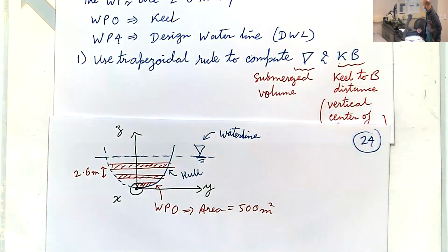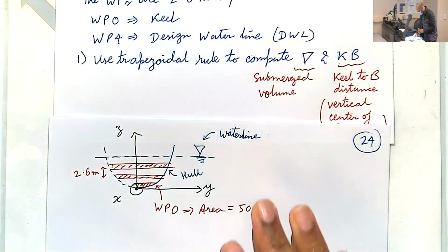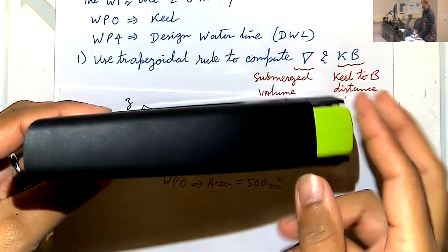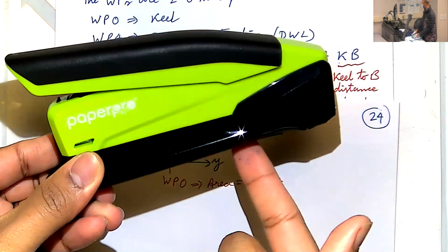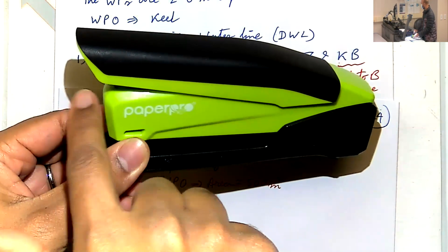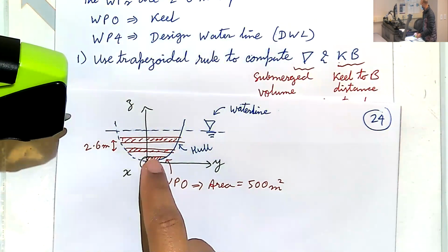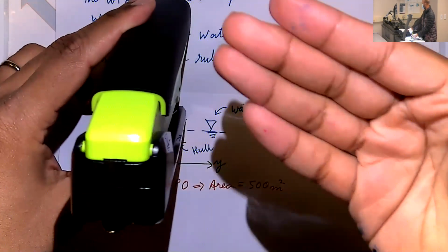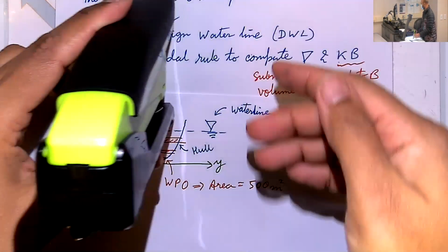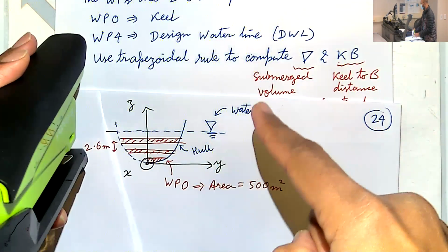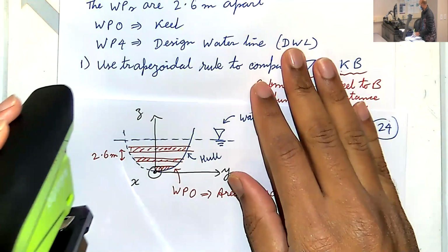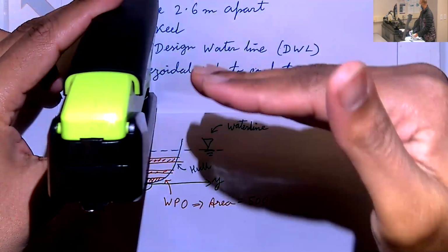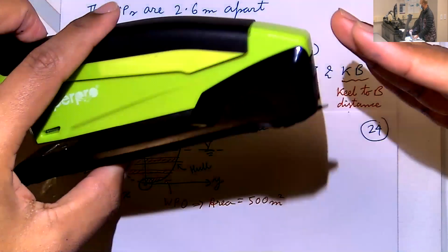Okay. So let's say this is my hull, all right? This is the deck, this is the keel. And that's the fore, that's the aft. So the view we are looking at right now is if I look at it this way, and the slices, the stations basically, that's the cross section that I've drawn. Now think about the water plane. The water plane is if you cut it this way, right? That's the water plane.